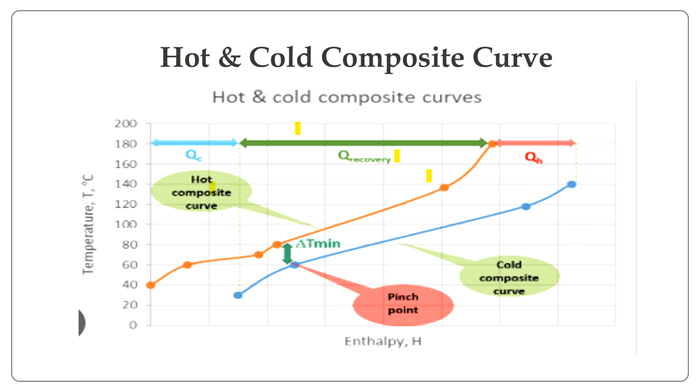During the transfer between these two streams in a heat exchanger, the cooling stream, that is the blue line, absorbs heat from the hot stream. In all processes, heat is transferred between the hot and cold streams. The cold line will absorb the heat and the hot stream will lose heat. So the delta T minimum is called the pinch point, that is the minimum temperature difference between the two streams.